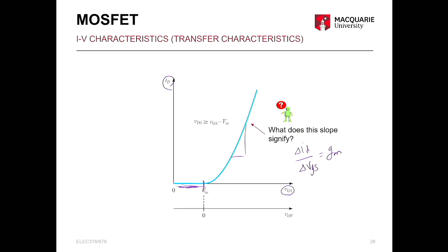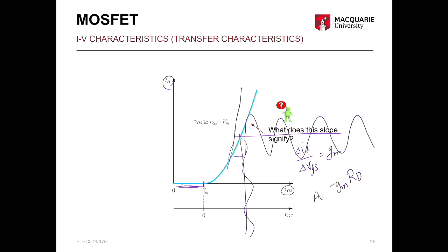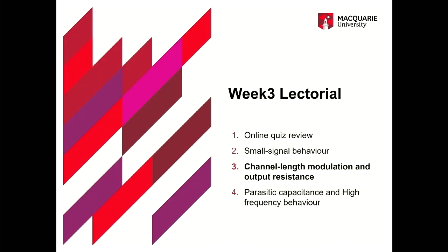And you found that the gain is gm RD. So the steeper the slope, the more your amplification will be, right? You can see that also just by drawing here and projecting that same point at the output. If the slope is very shallow, your output will be very similar to the input, and if the slope is very steep, you get high magnification.